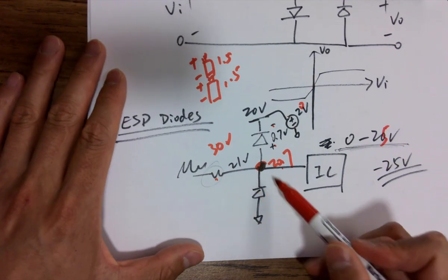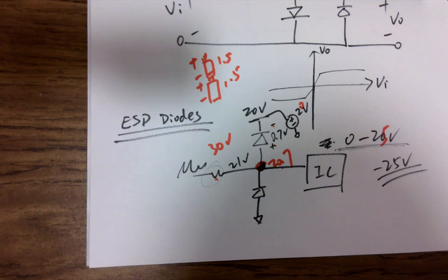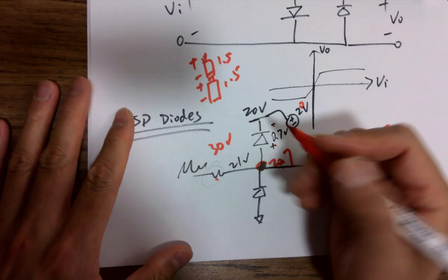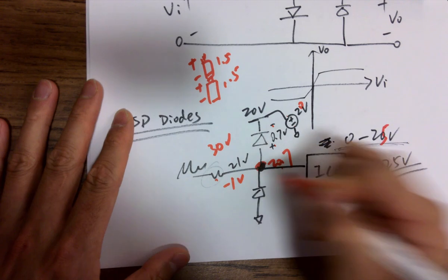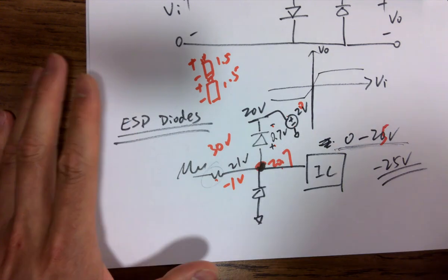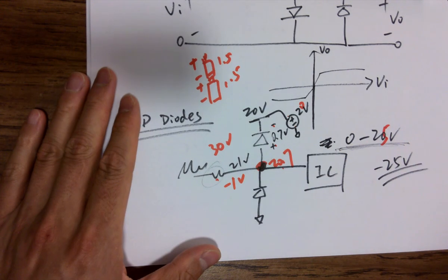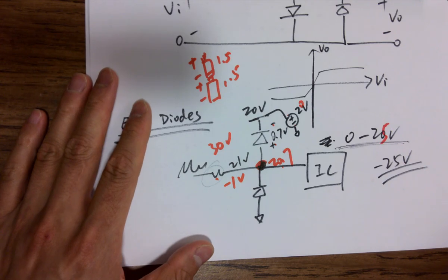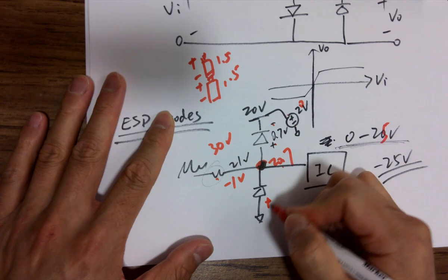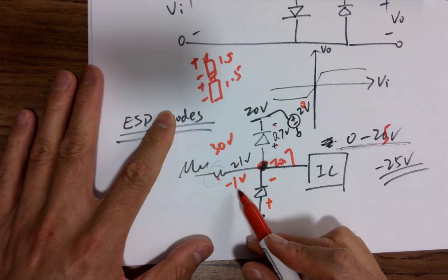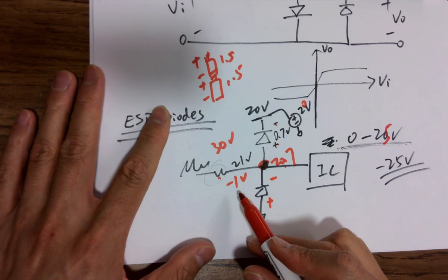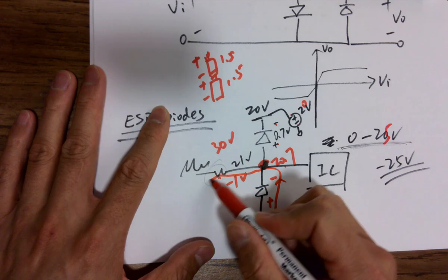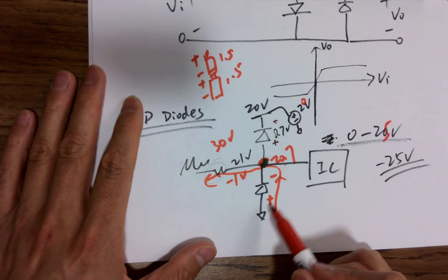That's for if it's negative voltage. For negative voltage, yeah. So if I have negative 1, for example, what's going to happen? It's going to forward bias it, yes, because 0 is larger than negative 1. So getting a negative 1 volt at the input is going to draw current from the ground and go through this resistor and consume it, right? So what's going to happen is